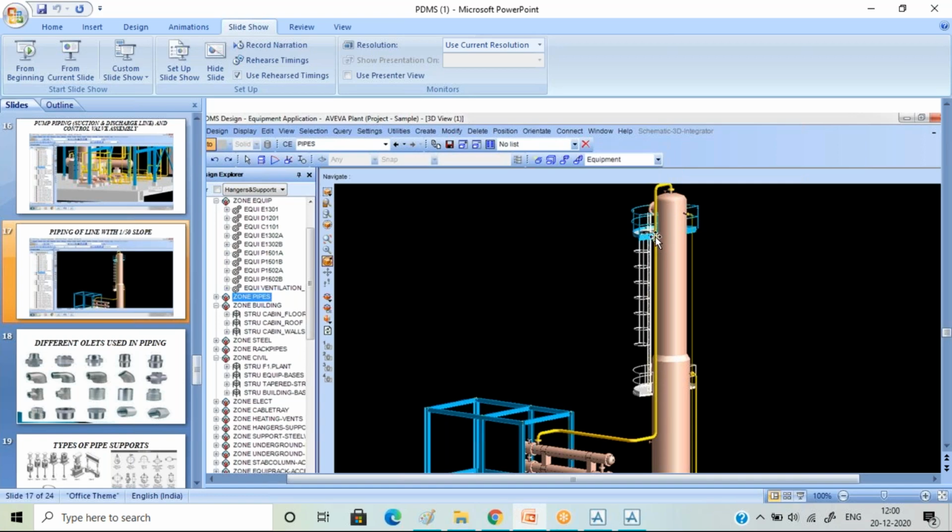Now since you're having an axial stop over here, the complete amount of growth coming into this section of piping will be transferred to this elbow. This elbow will behave like it's moving downwards, and when it starts moving downward, this one will move upwards. So there has to be no support over here, or if you want to place a support, it has to work perfectly as a fulcrum for this particular line, because the line cannot lift up at this position. If you're placing a support, it has to be somewhere in the center, working as a fulcrum about which both these elbows work.